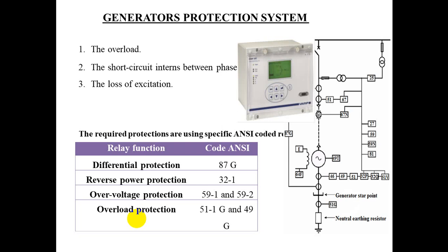Protection against rotor distortion. The cooling rates following shutdown at the top and bottom of the turbine casing are different, and this uneven temperature distribution tends to cause distortion of the rotor.